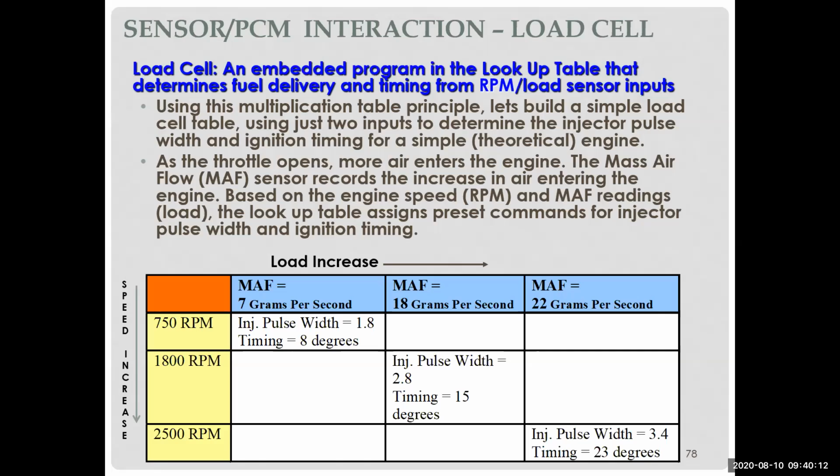So, and this is something if you're into tuning, or you've heard the term tuning, where people are tuning cars, what they're doing is they're breaking into these speed and load tables and changing the amount of fuel and the amount of timing, along with many other issues, given different engine inputs to change how the engine operates.